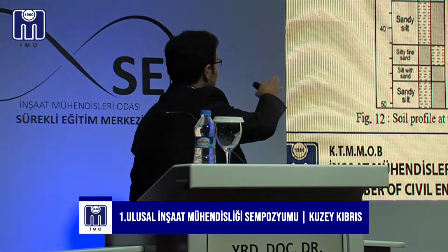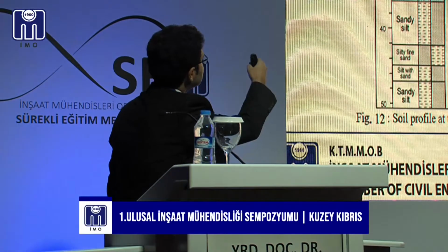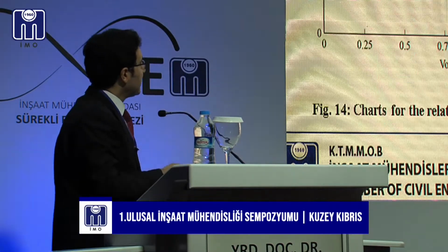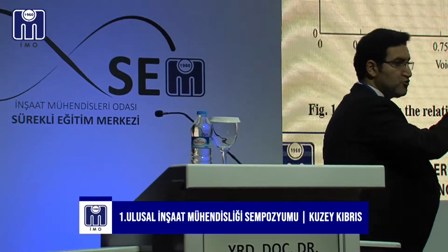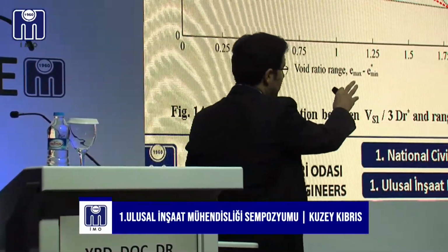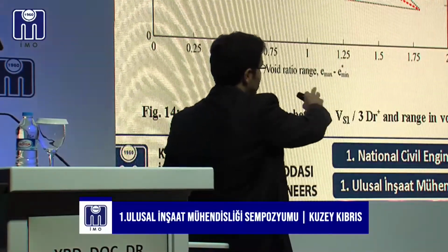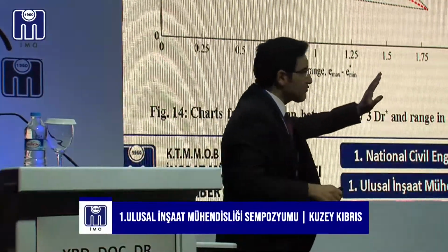Okay, these are the typical soil profiles. We can calculate the SPT N value and the shear wave velocity. And this is also an important graph. As you can see, we have to put all the data about Asahi City in this graph as relative density or corrected relative density versus shear wave velocity, but there is no good trend we can use.